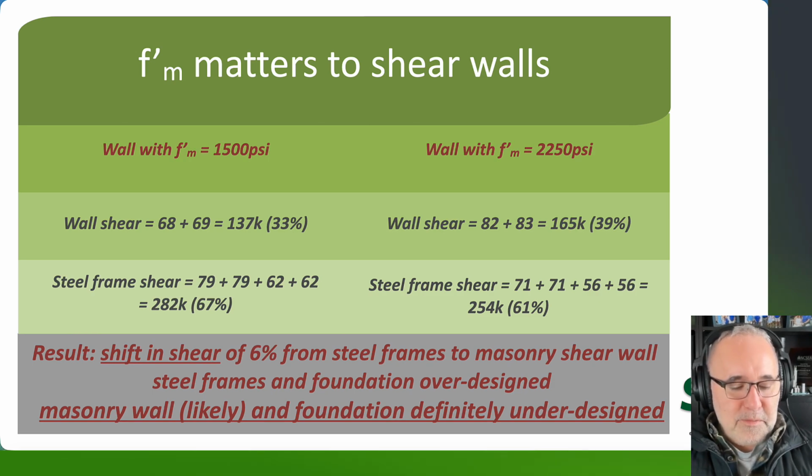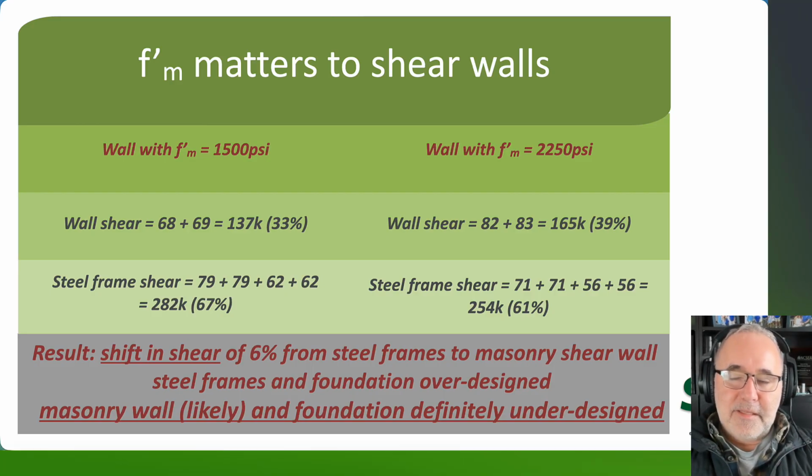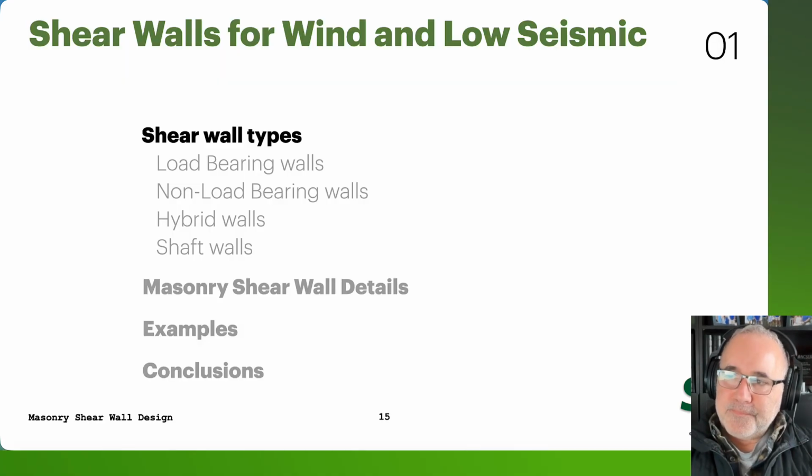What I always try to recommend people is, if you're using a finite element analysis for masonry design, be as accurate as possible, and get a design. And if you wanted to be conservative with your designs, choose to do that in the design step, not in the modeling and analysis step. So again, F'(m) matters, how we model these elements matters. And so it's just a really important tip to recognize.